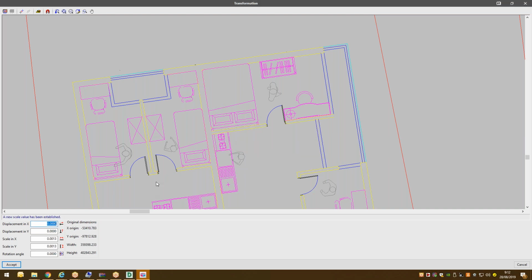So with this tool, I'm going to scale all the templates we have imported here in the software. Another possibility is to establish a visible area and also change the origin of coordinates. Normally, if we have different floors, we have to establish different areas and different origins of coordinates in the different floors. Okay. So we are going to accept here.